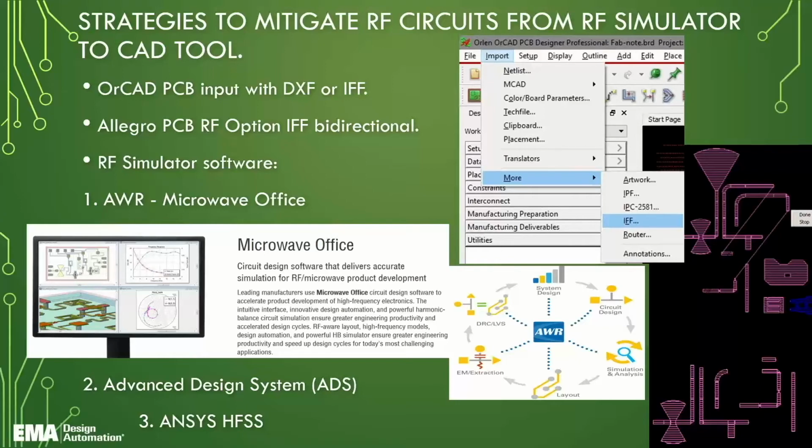What happens there is the signal's not being propagated out properly. What happens is you need to change the battery, needs more power. So there's a case where that's a class 1 product. If it fails, you know, you throw it away and you get a new one. Class 2 products usually are in medical, or at least costed enough that you want to go in there and change those. In those materials, it costs more to just throw that away and replace it. So you want to rework it or at least find out what's happening.